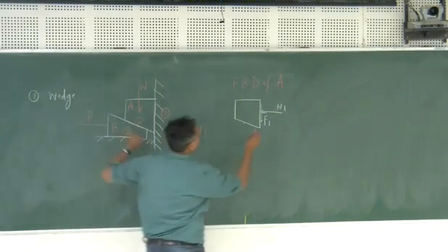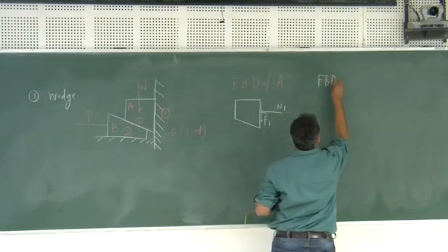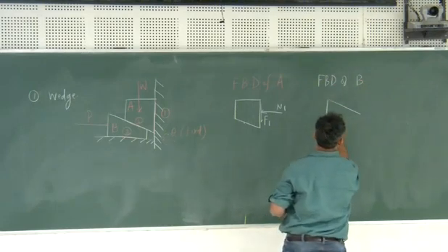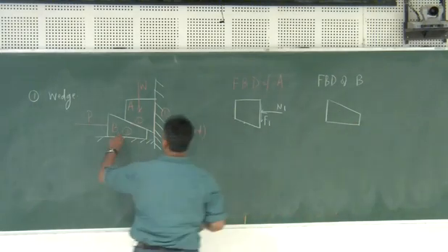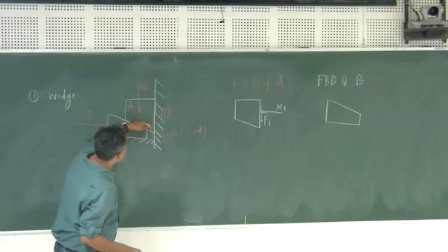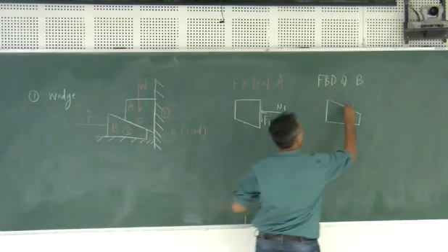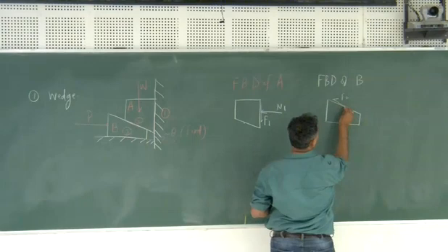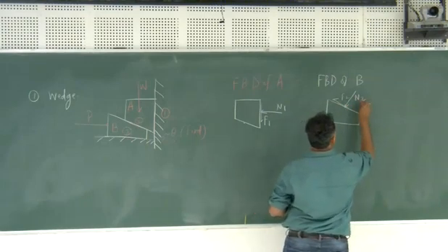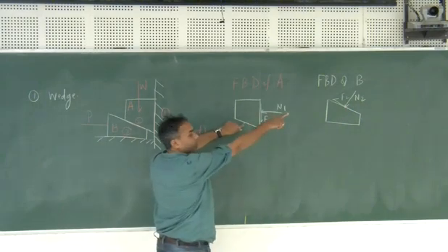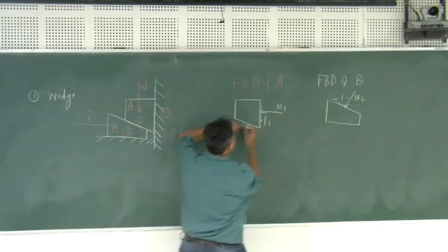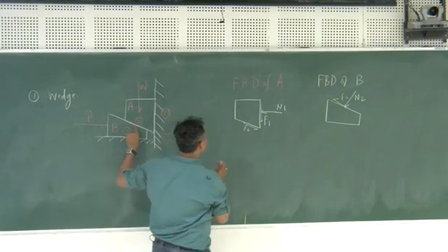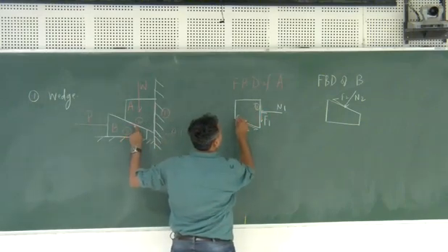So let us take the FBD of block B as well. If you take point B, this is going in this direction. It means that there is a friction in this direction about this. What will happen at this point? This will be just opposite to the direction of that. So F1 is in this direction. Here it will be this direction, because these two are the same contact surfaces. So contact number 1, this is 2.